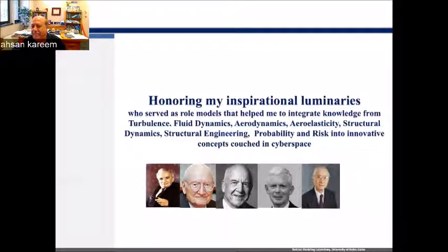And I think some people in mechanical engineering use the finite element method. Some people use spectral method. Some people also use boundary element, depending on the type of flow we are dealing with. But I think the current focus is going to be on finite volume. And that's where other issues come when we are doing fluid structure interaction: you interact the structural dynamics of a structure with a finite volume code, so interpolations have to be done in between.